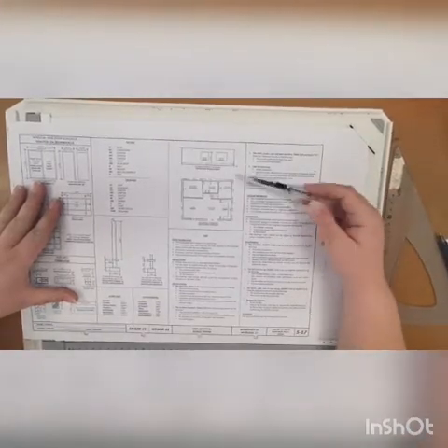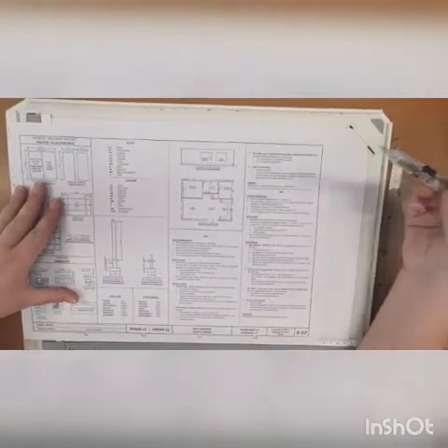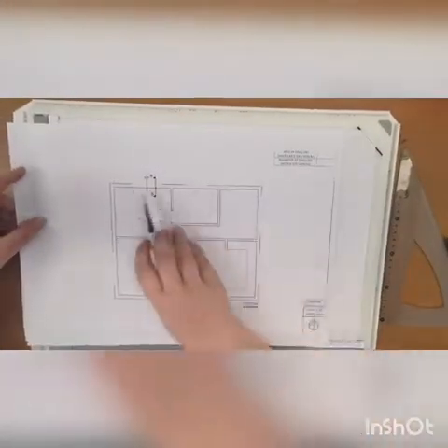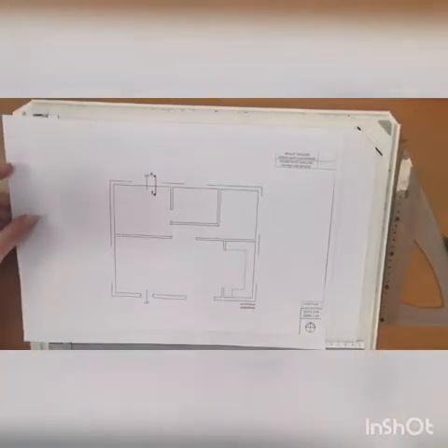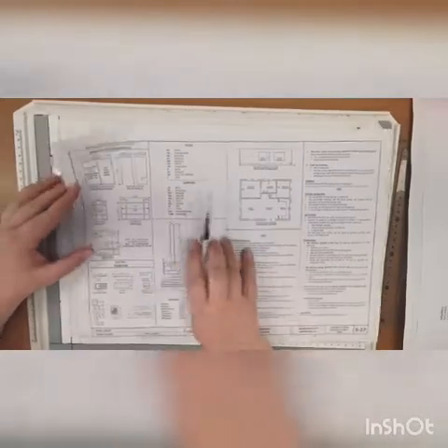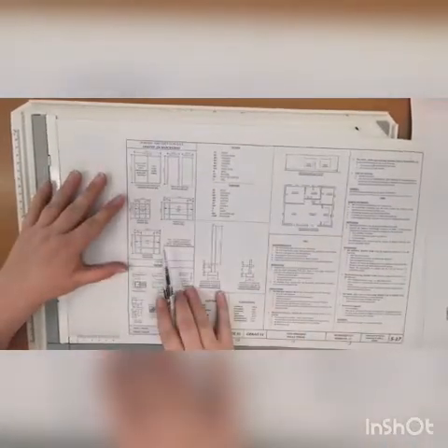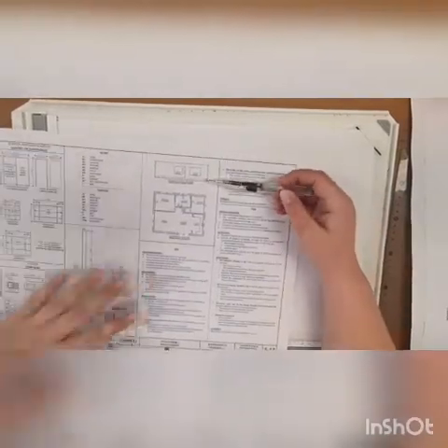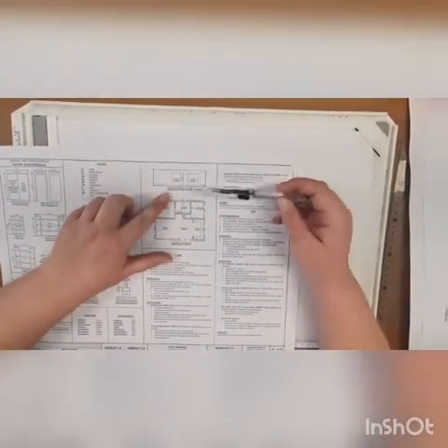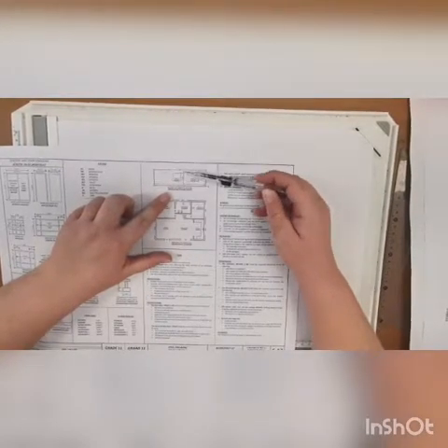When we're doing an elevation, we need to be looking at our floor plan. So you would be given a floor plan, or whether you've had to draw your floor plan, either way. Then you would be given what windows and doors are needed, as well as a window and door schedule. So let's start. Over here, they've given us an incomplete north elevation. That means they've given you the measurements they want.